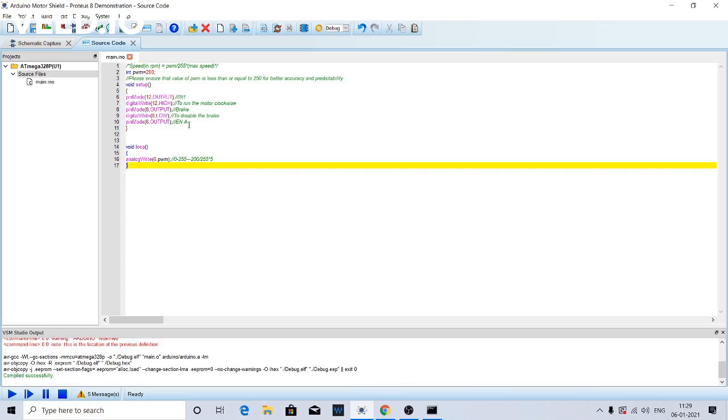So this is my source code. Here, variable PWM describes the speed of motor in RPM. Now the PWM is directly proportional to the average voltage. The 12th pin here is set as output. Now the average voltage generated is given by the PWM value upon 255 into 5.